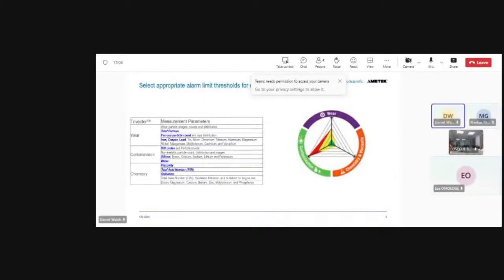Is the oil the right oil? Does it have the right viscosity? Is it broken down? Is it degraded? Or is there some sort of incorrect additive package present? So in any typical oil analysis report nowadays, it's not uncommon for you to have anywhere from 25 to 75 pieces of data being generated.